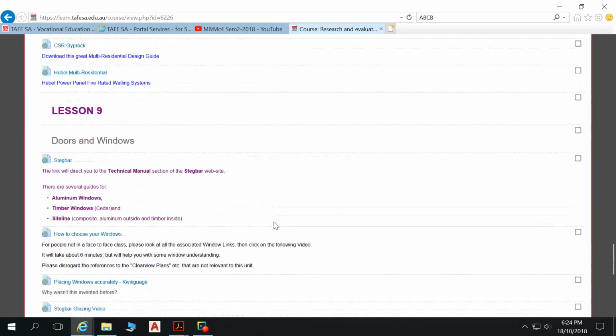Now, to make those building elements resistant to the incipient spread of fire, there are several ways we can go about it. One is we can just build everything in concrete. We can do concrete panels and have no penetrations through those concrete panels, or any penetrations that we do have fire stops on them, etc. And we can just do the whole thing in concrete, and then you're not going to burn it down.